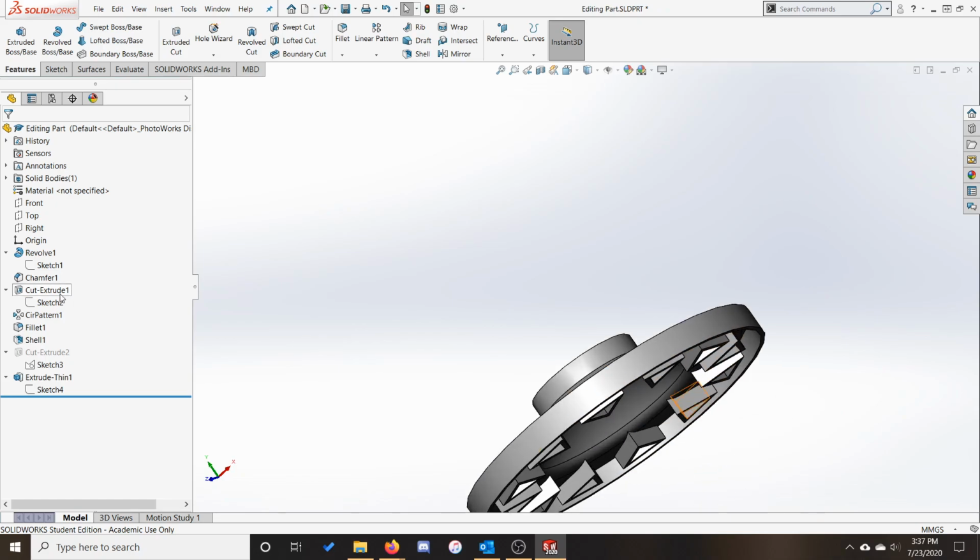The one extrude cut that we have is being duplicated by this pattern feature, which we're going to discuss further in a future lab. Importantly, the pattern feature is a child feature of the initial cut extrude, and just like we can't move children to occur before their parents, we can't move the parent to occur after their children. In order to fix this, we first need to move the child feature forward to occur after our shell, and then we can move the extrude cut.